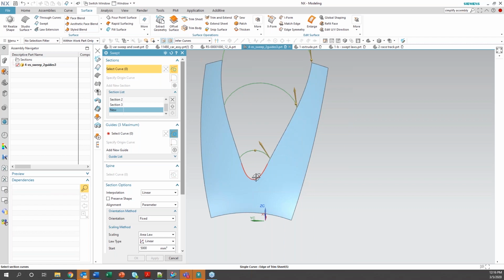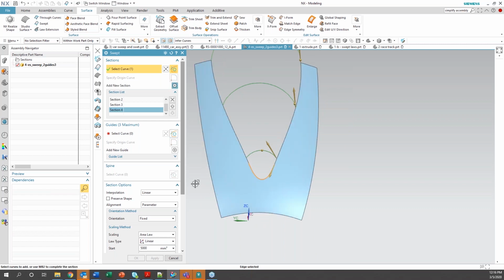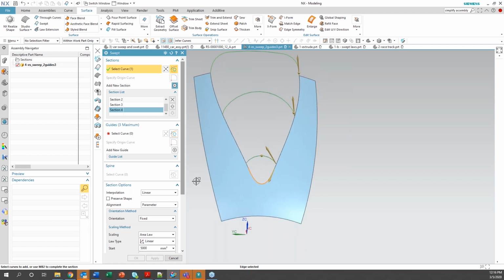Yeah, that one there. Hey, Richard, we have someone wondering which bundle this is that you're using. Oh, good question. So a lot of the functionality does come with a Mach 1, things like the extrude, the revolve, and the ruled surface. When you get into this swept and variational sweep, you would need to be in a Mach 2 bundle.